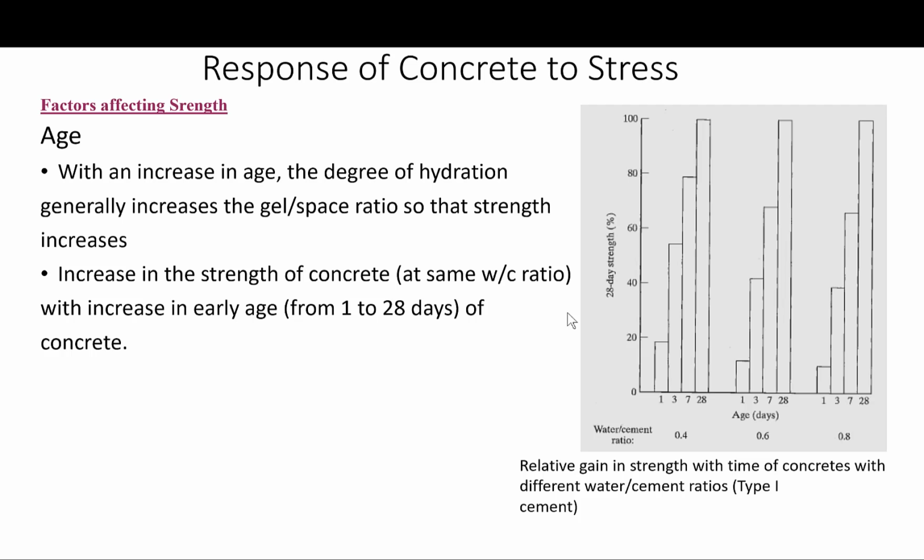Okay, so in practice, it is common to obtain 7-day as well as 28-day compressive strength. So it would be very useful to extrapolate a 28-day strength from 7-day or other strengths. Of course, this depends on the cement type and the curing temperature. As a general rule, the ratio of 28-day to 7-day strength lies between 1.3 and 1.7, but is usually less than 1.5. Generally, the higher the rate of early strength gain over the first 3 days, the higher the ratio of the 7-day to 28-day strength.